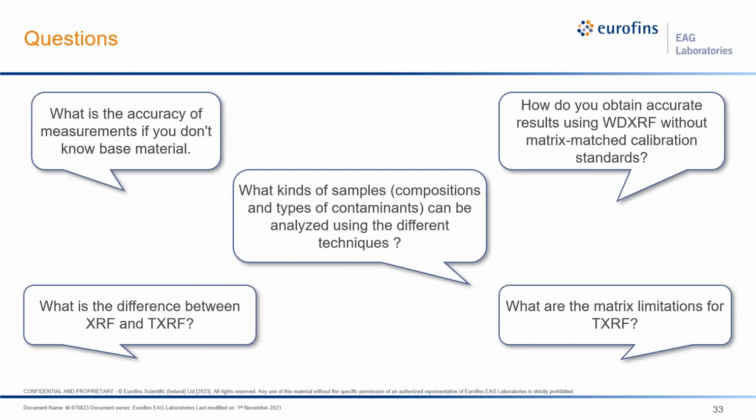We had a few questions that were submitted that I'd like to go over now. One of those would be, what is the accuracy of measurements if you don't know the base material? And to kind of go along with that, this other question, how do you obtain accurate results using WD-XRF without matrix matched calibration standards? So with XRF, we have two ways to quantify results.